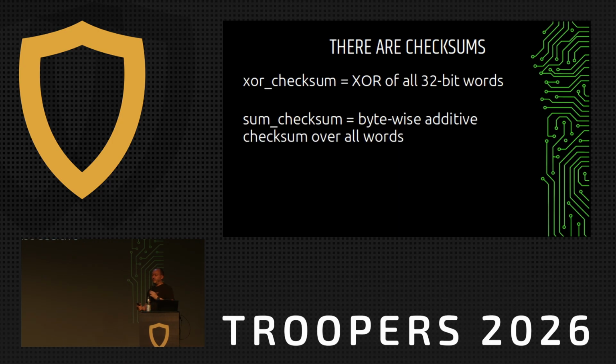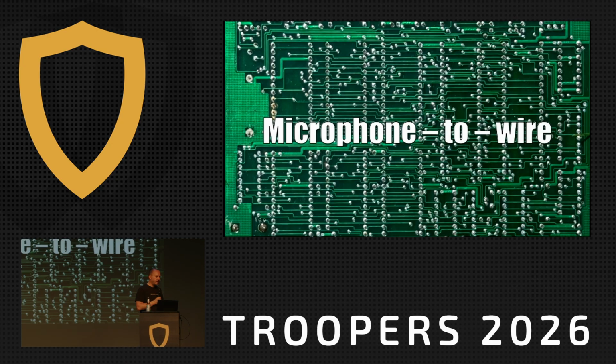Right, and the frames in DUOX Plus use checksums, very, very simple checksums. Usually there is some magic constant involved, not here. Basically, there are 2 checksums. There's an XOR of all the words, so basically 4 bytes that XOR everything and they are added together. And then there is 1 byte, which is the sum of all the bytes, modulus 256, of course.